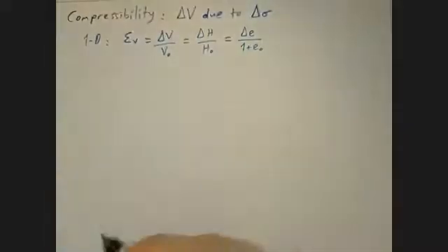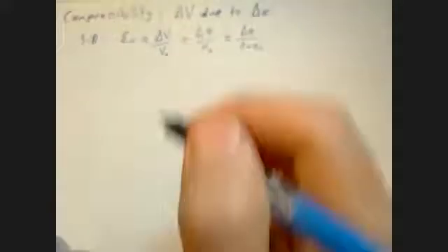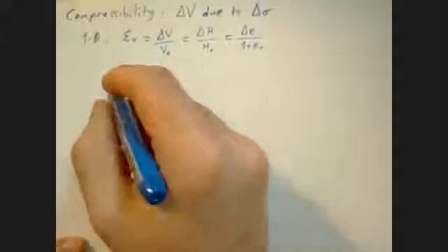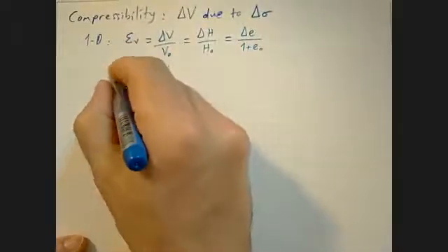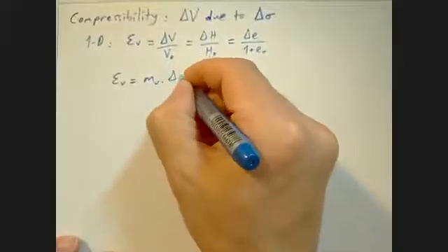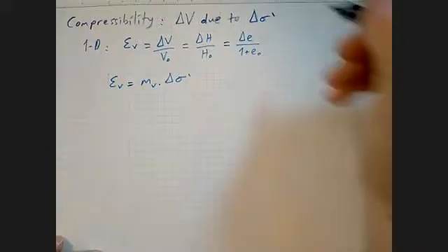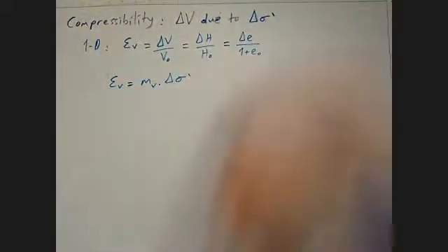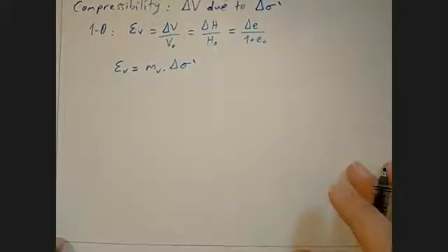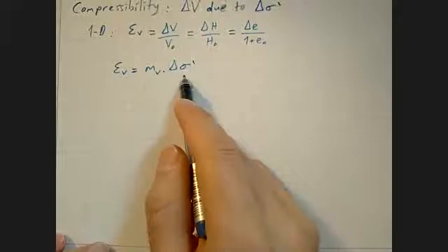So the initial methods or models consider the soil to behave in a linear manner, linearly elastic manner even. And of course I need to mention it happens due to effective stress changes because we are compressing the solid structure. So the most primitive approach to this is a coefficient, a constant, times change in effective stress.